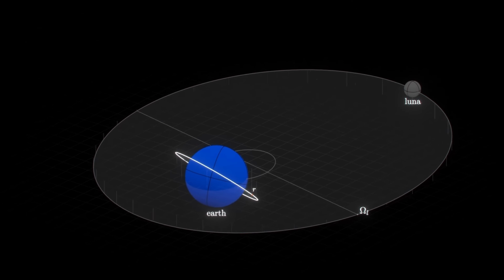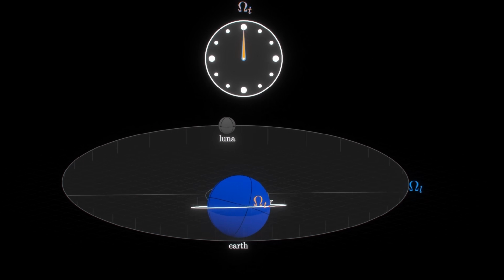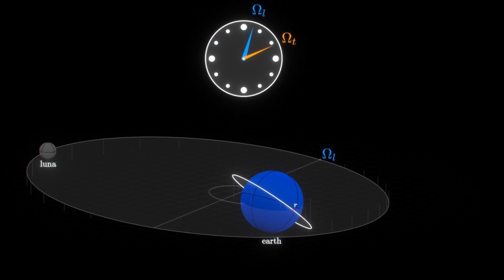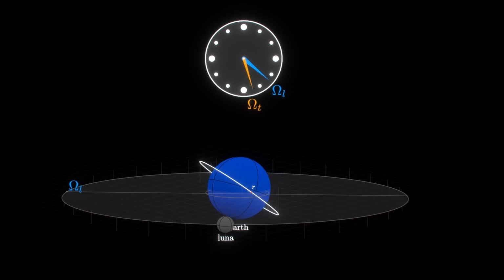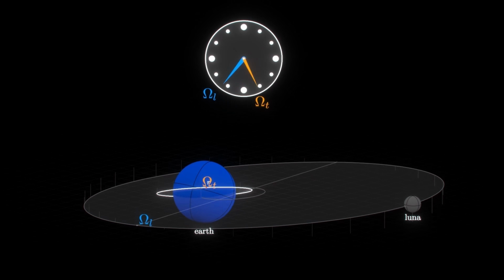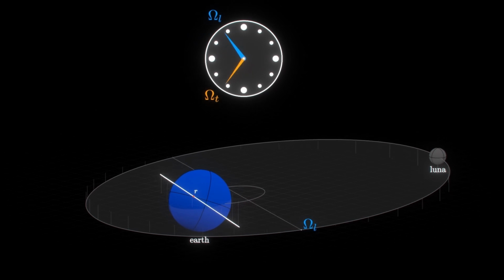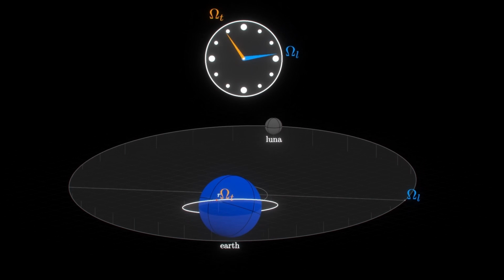cycle. This means the precession rates of either orbit work kind of like a clock, with the lunar precession being analogous to the hour hand and the target orbit precession being analogous to the minute hand. This is really useful in that it makes maneuver planning in accordance with the precession cycles easier.